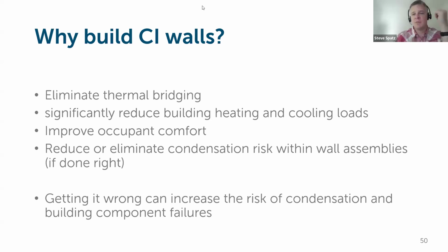So if you have an open rain screen or some sort of exterior finish, siding that has gaps between the cladding for an aesthetic or finish standpoint, you'd want a larger gap behind that material and the wall behind it to allow for bulk water to escape. But if we're just talking about drying for convection purposes, then yes, just a small capillary break is enough to create that capacity for drying to occur.